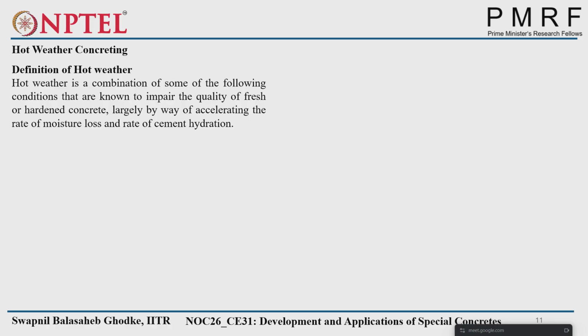So what we saw in cold weather concreting is, if we go for placing, we have to do some preparations. We can go for material heating also, of water or aggregate. Curing during protection is very important, specifically for early ages, and the early age period depends on the temperature at which we cast the concrete, suppose 5 degrees Celsius, 10 degrees Celsius. And ultimately the thumb rule is, what does the thumb rule say? Two conditions have been given by the thumb rule,